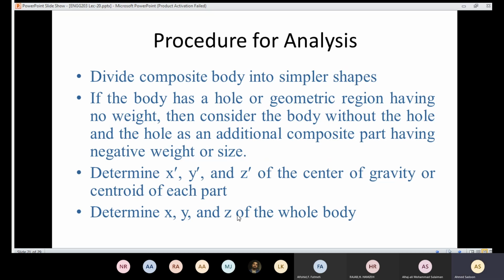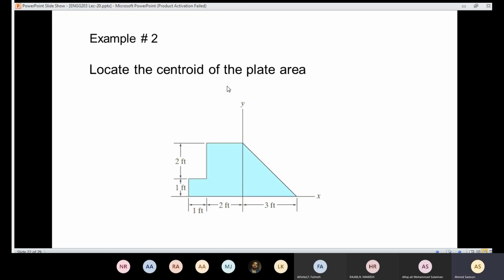To understand this more, we need to solve example 1, so that we connect all these ideas together in one example. So here we have a composite shape, like you can see here. The reference is located here. So the reference for me is here, x and y. The reference also could be there. So we put the reference here. It means that I'm going to locate the x and y depending on that reference. So here the value of x is 0 and the value of y is 0 as well.